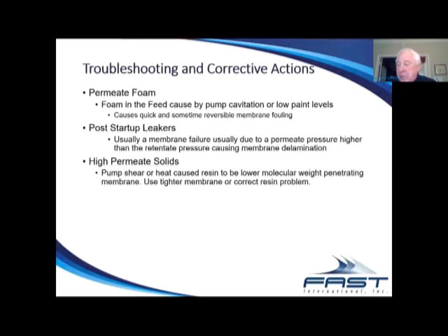We had one customer that I happened to be after in the install that we had this high foaming condition. And when we started it up, we were getting the expected flow rates, in that particular element around 5 to 5.5 gallons per minute. But within 1 hour, it was down to like 1 gallon a minute, and the foam was there.